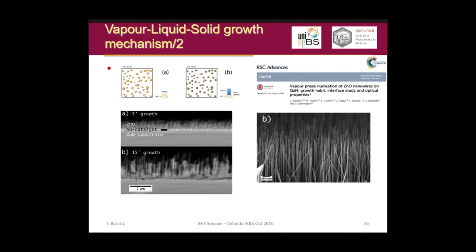But we also observe that you can have the ball at the beginning of the material, like in this SEM image of a forest of nanowires growing upward. And so in this case you have root growth, and the zinc oxide material grows, and its dimension is decided by the dimension of the catalyzer particle, okay? You can have growth of nanowires also without catalyzer, but you have sparse, low density, so maybe it's not useful for application.